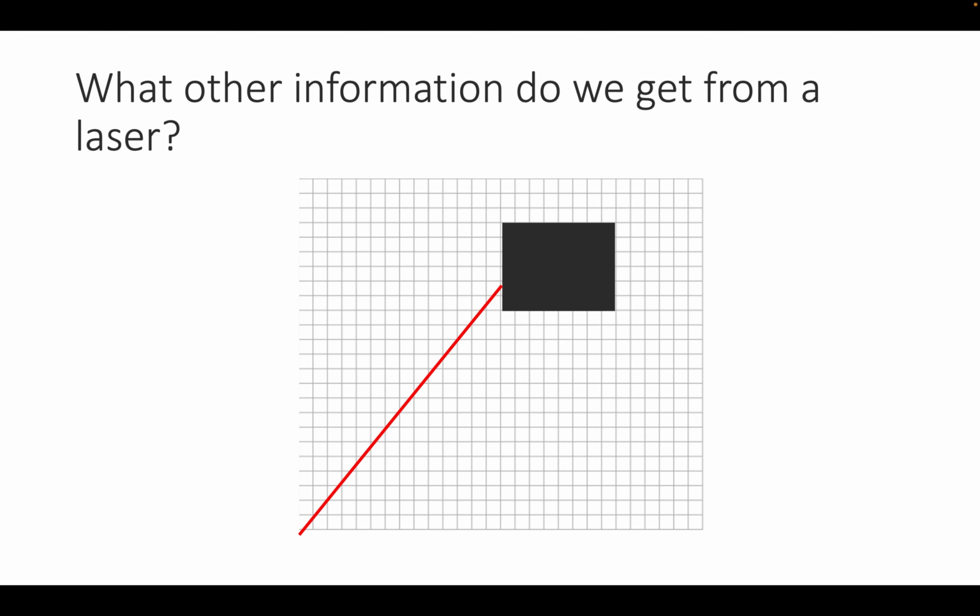All right, so there's one more thing for this module. So far, we have only used the final point where the laser hits an obstacle and said, well, this is a grid cell that we can update now and increase its probability to be an obstacle. When we fire the laser, we learn a lot more, however. We know that all of the grid cells that it has passed are actually empty. Otherwise, it wouldn't go to reach the obstacle. So what we now can do is, instead of just updating the pixel where the laser hit, we can also update all the pixels that come before it.